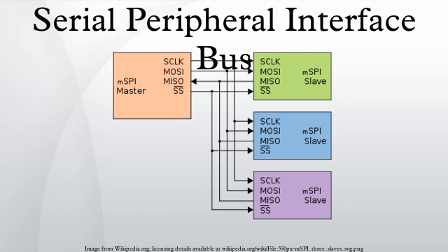Every slave on the bus that has not been activated using its chip select line must disregard the input clock and MOSI signals, and must not drive MISO. The master must select only one slave at a time.